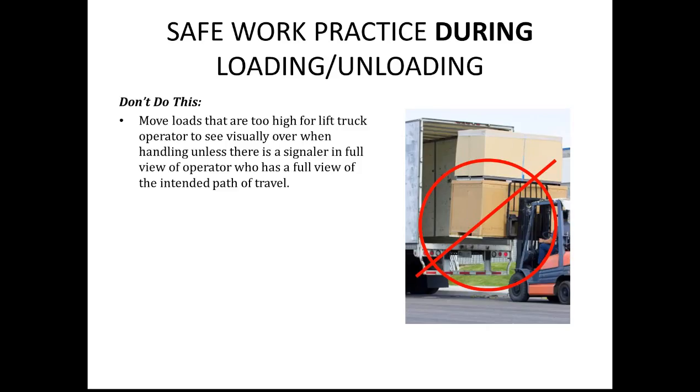But in this case, you don't see anybody, and this fella runs a high risk of either knocking over that upper unit load, or striking the side of the unit load against the side of the trailer. So in cases like this, which are often unique, you should have a spotter that helps the forklift operator load the trailer.